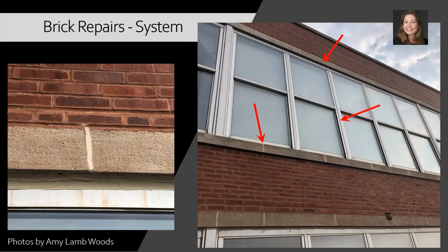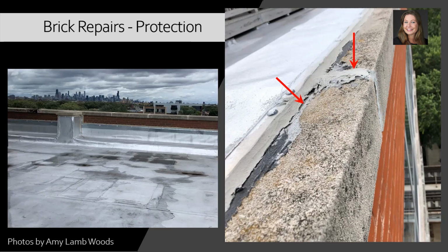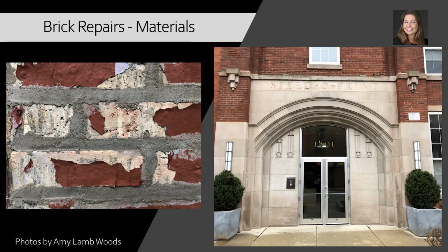You've got to put flashing systems in above these windows. We've got to make sure that those perimeter sealants around the windows are maintained and sealant joints in the top sides of the window sills are maintained. They have to be protected. These are some examples of a new roofing, but where a lot of those sealants are not done ideally, like they're not put in a great location and they're not lasting.